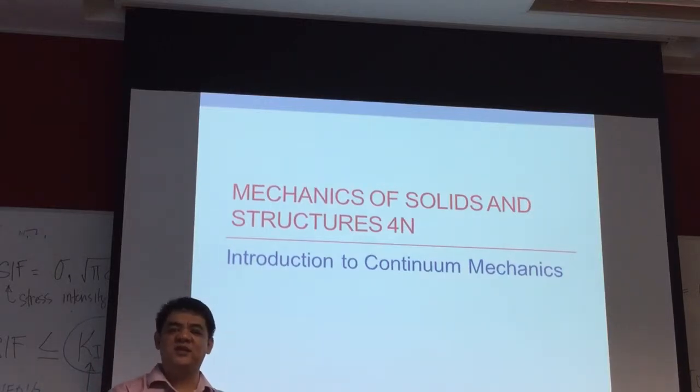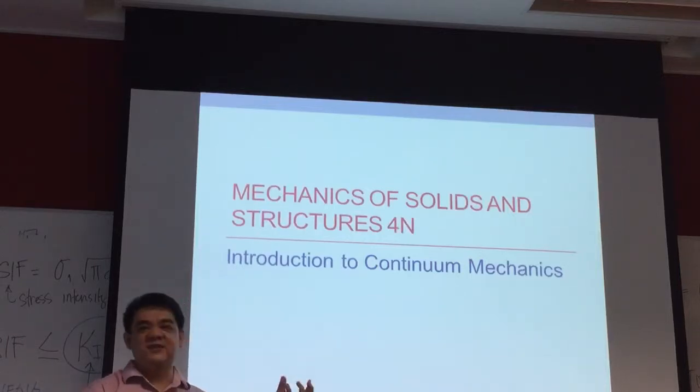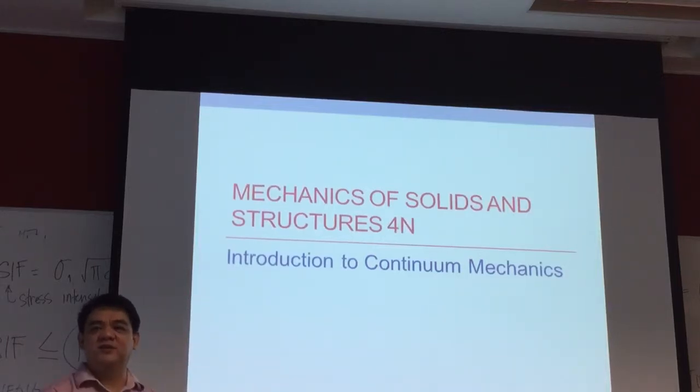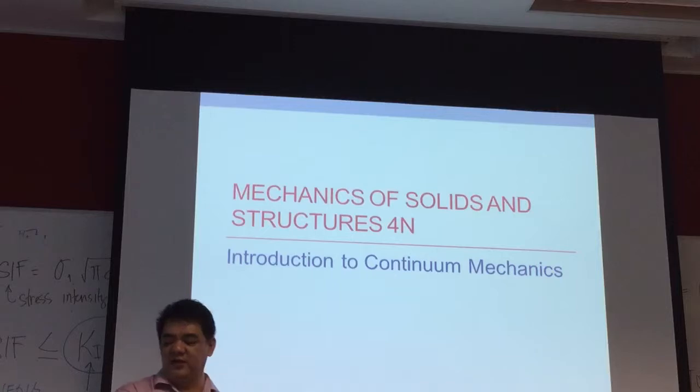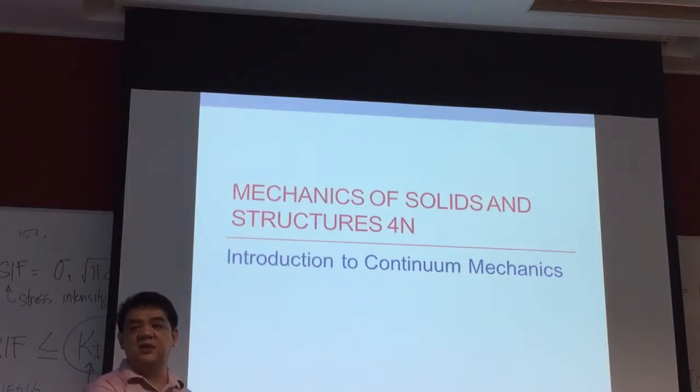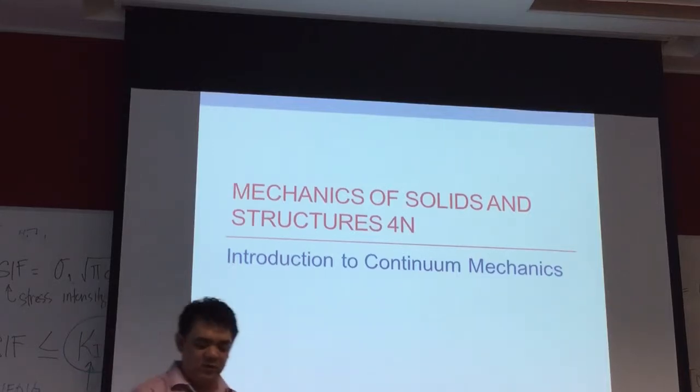Finite element is quite easy. Draw a figure, put in some fixed thing there, put in a load, you get pretty pictures. The question is, how do you know your results are correct? Again, you go back to the basics of solid mechanics. So it's always best to start your design or your calculations using the elementary mechanics theory before proceeding on to more advanced tools.